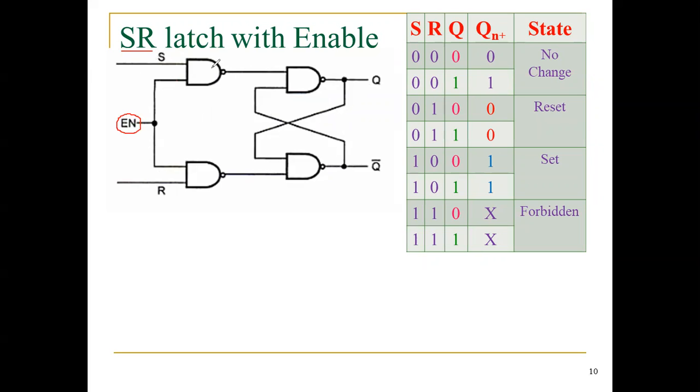So for that, you should be thorough about the truth table of a NAND gate. According to the truth table of a NAND gate, if any one of the inputs equals 0, the output will be 1. If all the inputs are 1, the output will be 0. With this fundamental, I'm entering into the SR latch, that is the SR flip-flop.